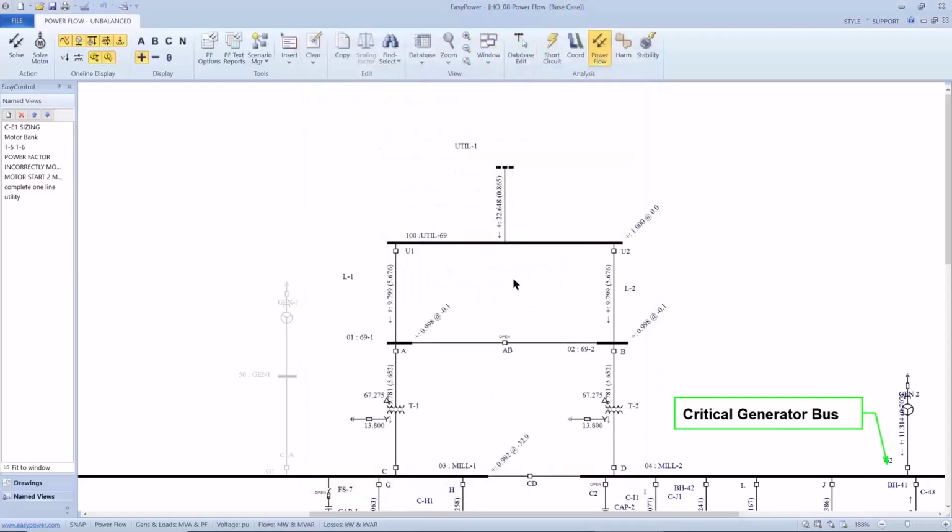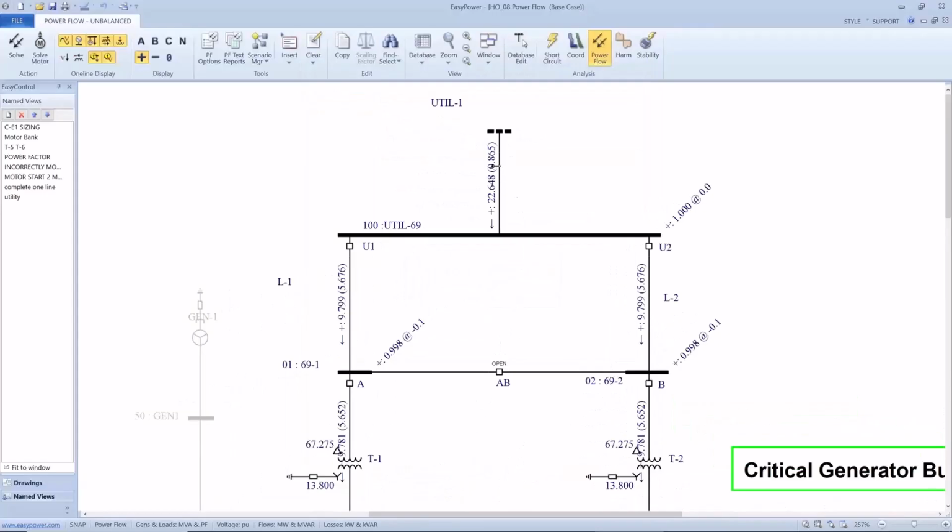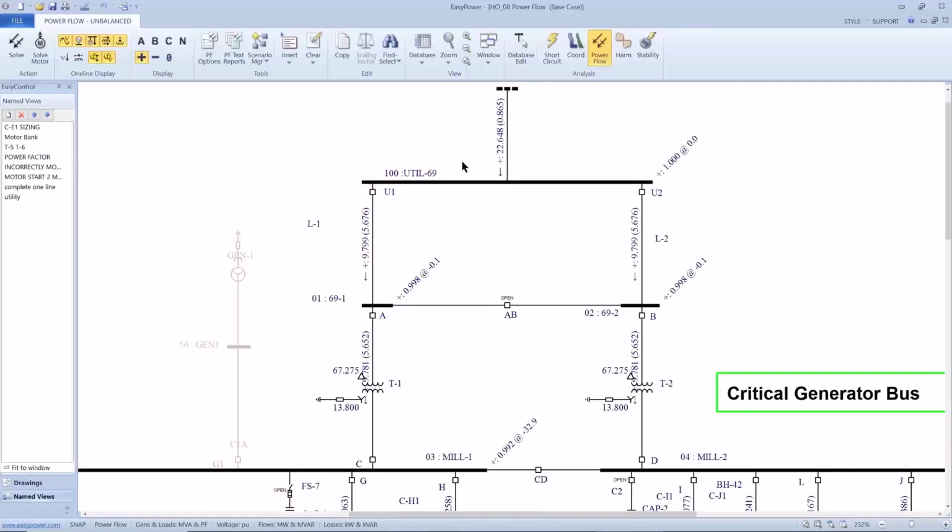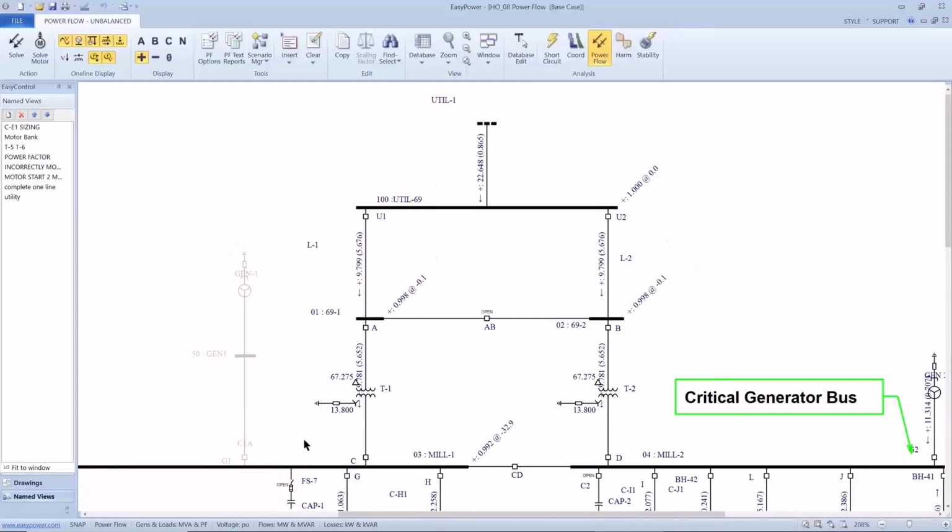And we can say with the motor loads that we have, we've got a 0.865 power factor without those capacitors included. So let's turn those capacitors on. Now another feature that's part of the PowerFlow module is the ability we call Smart Breaker. I can just double click on the breaker and it will activate and then recalculate the PowerFlow solution.